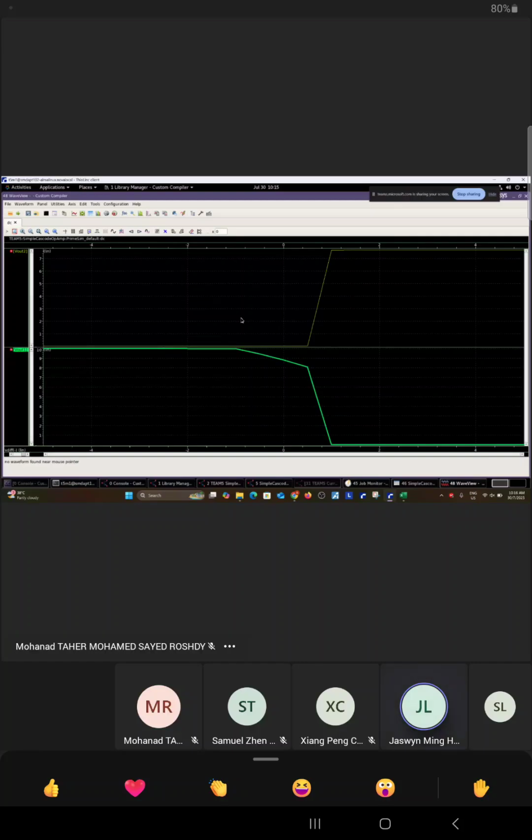Let's look at the more positive region first. Maybe I give an example, let's say your gain is 2 times. So your output is actually V in times 2. So this slope is simply a constant gradient, right? This is where your gain is constant, and this is where no matter how much more your V in increases, your output is just capped at this limit.